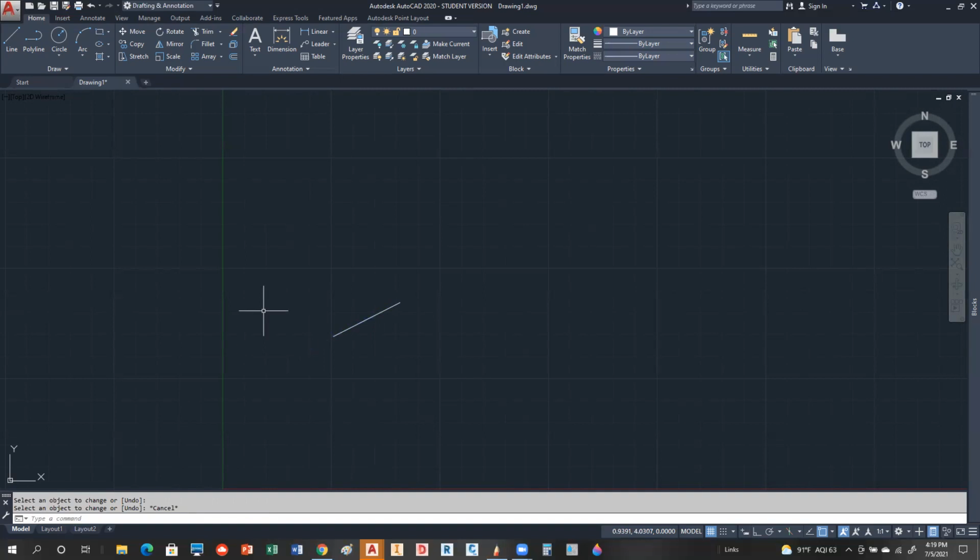One of my favorites is total, because total allows you to have a length or an arc of any size, and then tell it, well, I want this to be exactly 5 units. Right now I have no idea how long this is, no idea at all. But if I go into the lengthen command and tell it total, I can say I want this thing to be exactly 5 units. And again, notice where I pick it, it holds it from the opposite end.